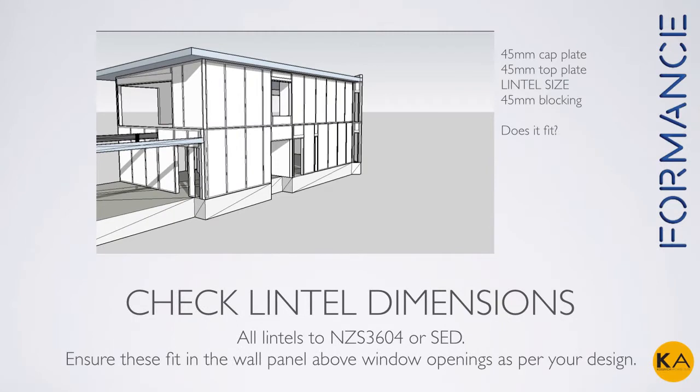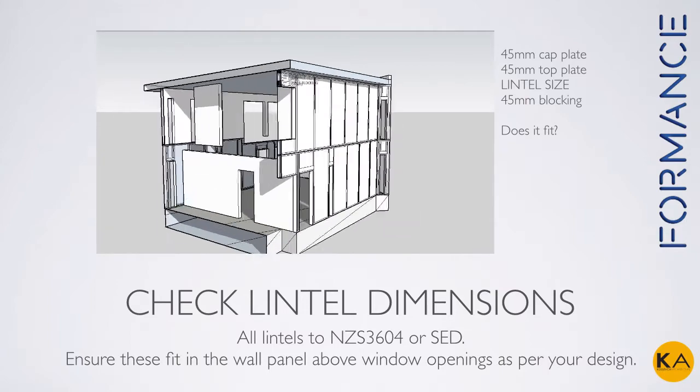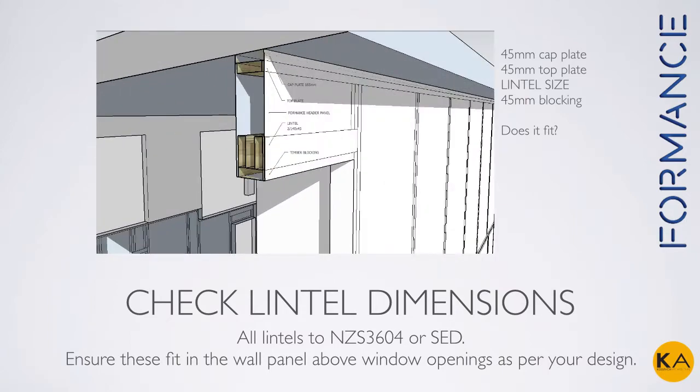Lintels for Formance panels have to be designed to New Zealand Standard 3604 or specific engineering design. But in both cases, the required lintel sizes have to be resolved in the details as well, just reviewing whether the lintels actually fit in the available space above the window, with all the timber blocking, the bottom plate, the cap plate, and the actual dimension of the lintel.